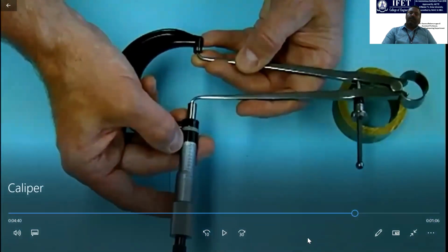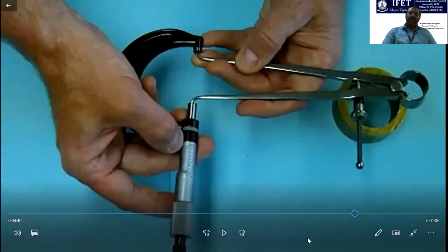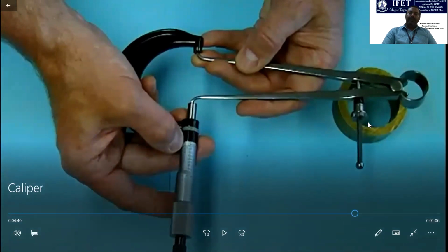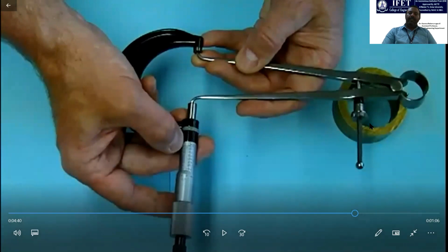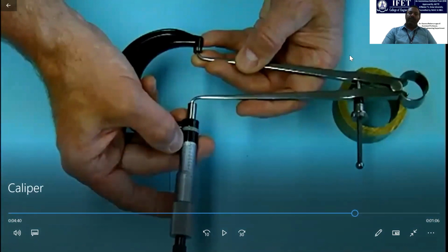So one thing you have to keep in mind: you can ask a question, why do we need to use the caliper instead of the same micrometer or any other direct measuring instrument to measure the inner diameter or outer diameter of a hollow section? There are limitations. For example, if the outer diameter of the hollow section is very large, these screw gauges have measuring gaps that are very limited, standard. So it's very difficult to measure these diameters, and we cannot insert the whole section into the screw gauge.